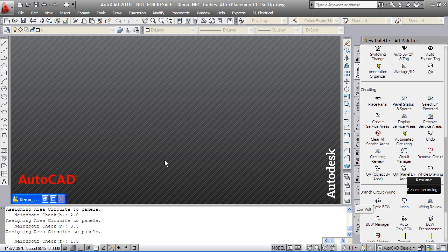You can also decide to have all motors circuited separately. Heaters will circuit to the same panel rooms as receptacles. Large motors will look to the project parameter wherein you, the user, decide to direct them to motor control centers, the main distribution panel, or regular branch circuit panels that also service receptacles.